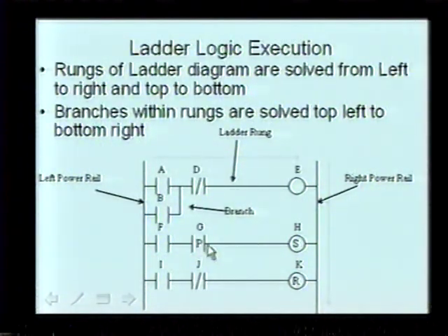When you look at a pulsing or a one shot, basically whenever F closes, this will toggle high and then it'll turn itself off. So H will just set, which means it'll latch itself in. So you can actually have fairly complex code in RSLogix or in ladder logic programs that are not limited just to the Boolean identities. If you have a set or a latch, you must have a corresponding reset or unlatch signal.